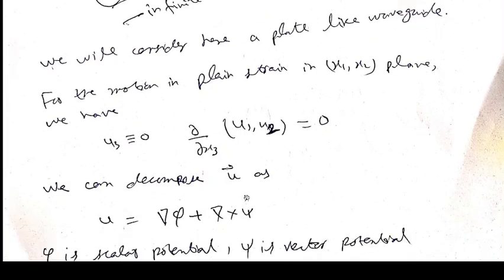Now we will use only boundary conditions to find the dispersion relation. To apply the boundary condition, because you know that when we have a free boundary, we suppose that our stresses vanish at the boundary of the plate, either at x2 equal to plus h or x2 equal to minus h. At the boundary the stresses will be equal to 0.